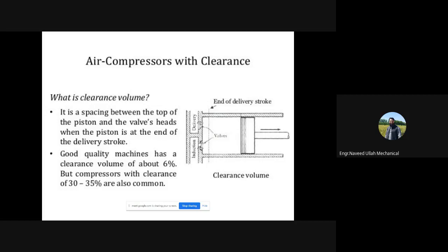Okay, where previously for the same data and for the same pressure ratio, the work consumed by the compressor is calculated, and then the isothermal work is calculated, and then they found out that for the isothermal process, the work consumed is less as opposed to the one that we calculated earlier for polytropic process, and we will be having some isothermal efficiency.